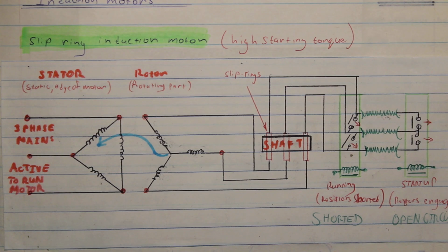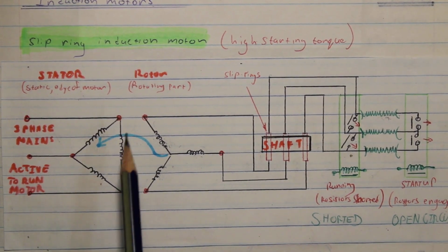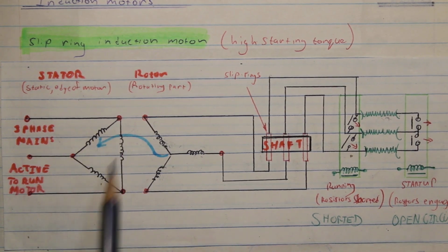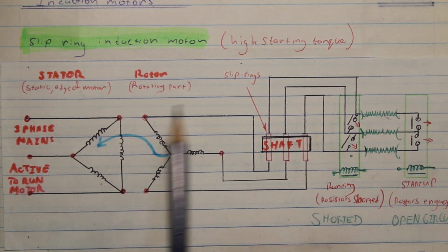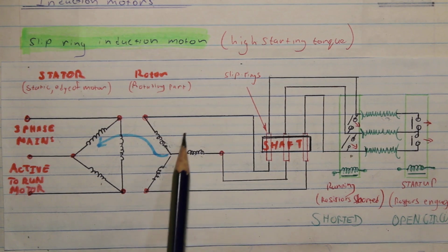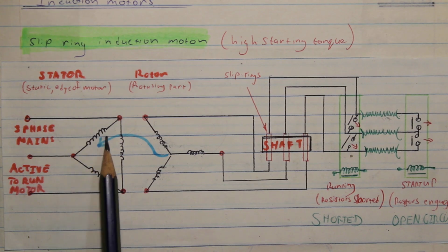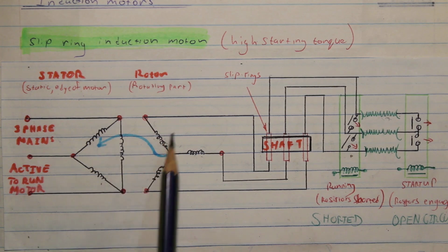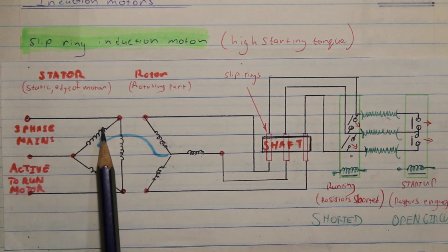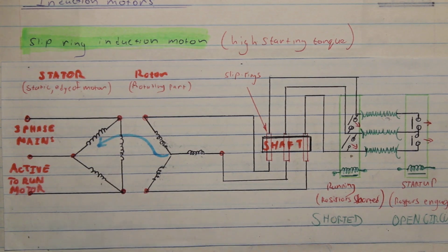And when it says it's at 5% slip, that means that the stator's rotating magnetic field is still going at 50 Hertz, but the rotor is going at 95%, so 5% slower than the rotating magnetic field. So the rotor is only experiencing 5% of this rotating magnetic field, and we'll see how that impacts the problem.